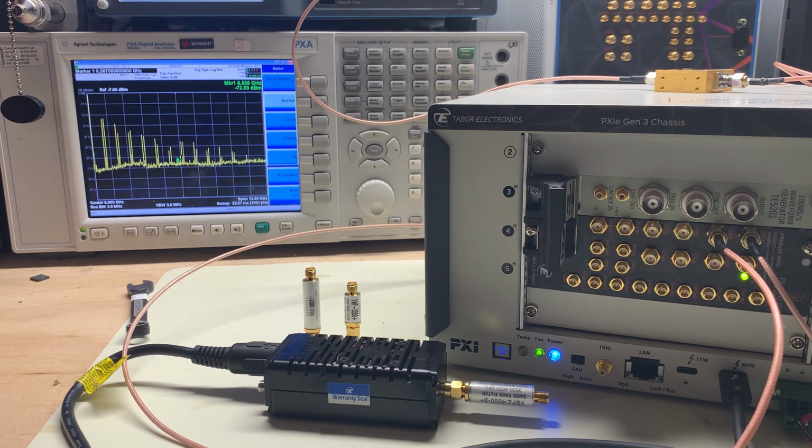So one thing that we can do is change the interpolation of the clock. We can also change the sample frequency. A typical Proteus arbitrary waveform generator goes up to 9 gigasamples, but the higher the sample rate you get, the lower the effective ENOB, equivalent number of bits, and also the vertical resolution decreases.